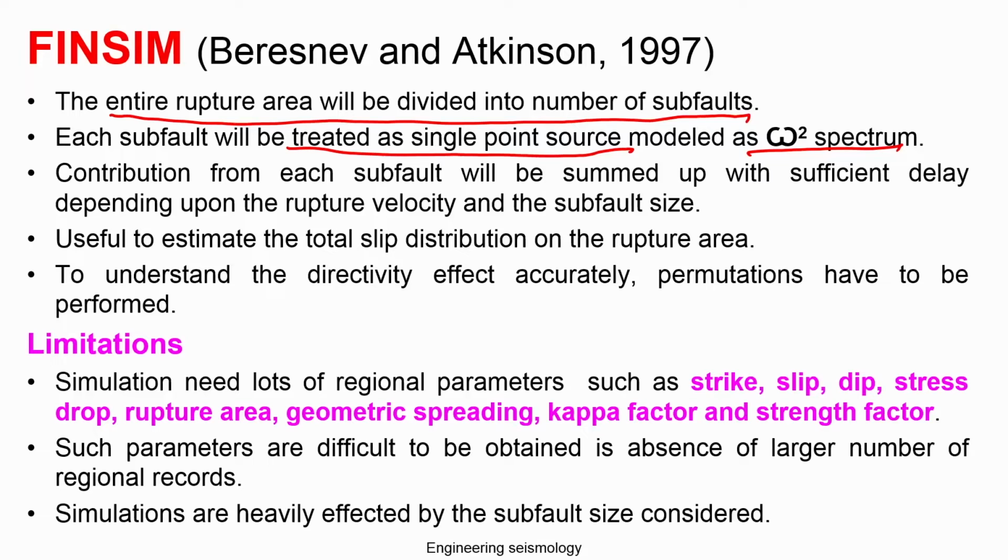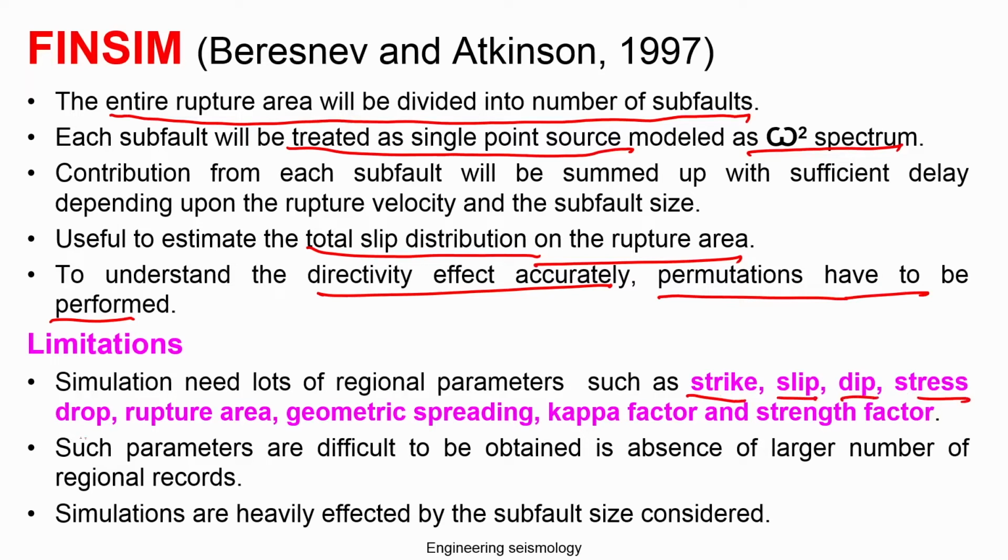So, it is useful to estimate the total slip distribution of the rupture area and to understand the directivity effect accurately. Okay. So, parametrizations have been performed. So, the directivity and the slip distribution can be handled easily. The limitation is that the simulation needs a lot of regional parameters such as strike, we know what a strike is, slip, dip, stress drop, rupture area, geometric spreading, kappa factor and strength factor. So, the kappa and strength factor you can get from the minor earthquakes recorded in the region.